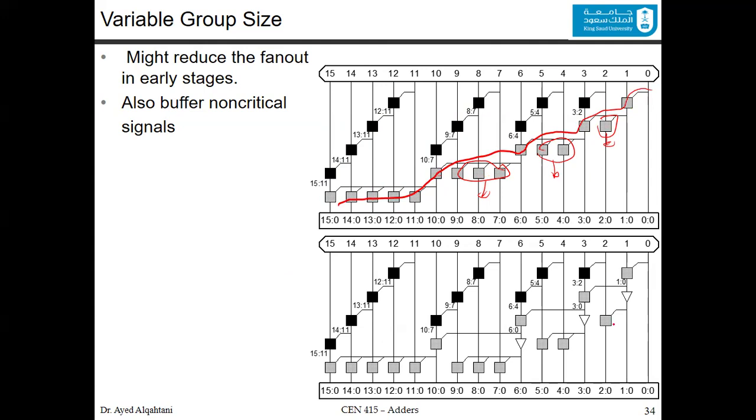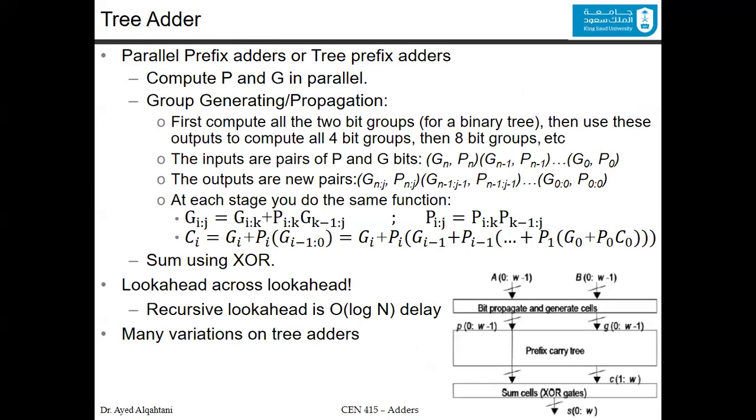So these are factored out like this. Now, in the critical path, there is only the lowest number of fan out. So you have only fanning out to 2, fanning out to 2, fanning out to 2, until you reach the end. And at the end, you are having this fan out. You cannot do it. So if you want to fan out, the delay will increase. So that's the idea about if you have variable group size and how to fan out using the carry increment adder.